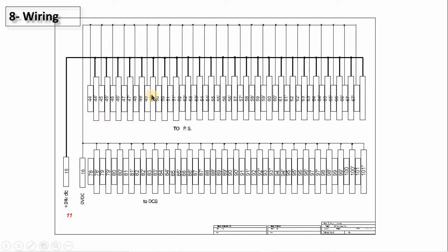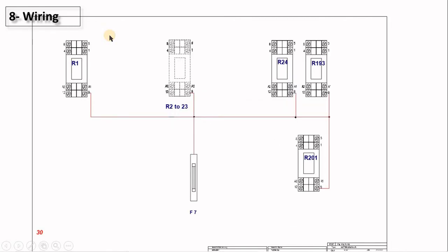Now you can see here in these terminals, we have a supply, the 24 volt. This is a 2-tier or 2-level terminal, and we connect the power, the 24 volts, to this one, and then the return will go somewhere, and so on. So again, it depends on the method the company uses. You will produce your drawing.